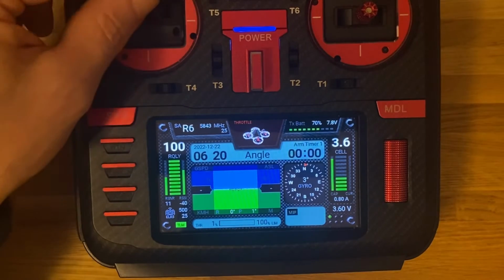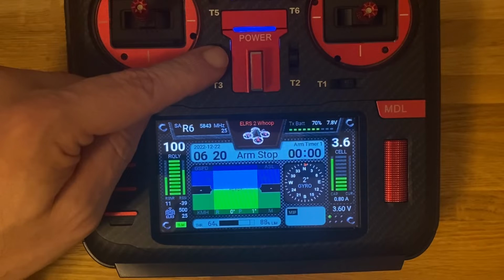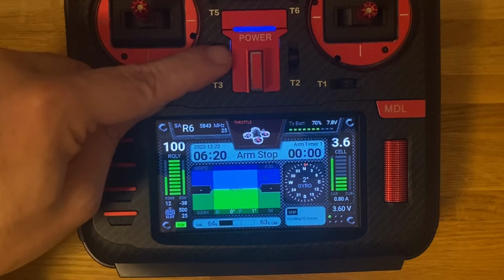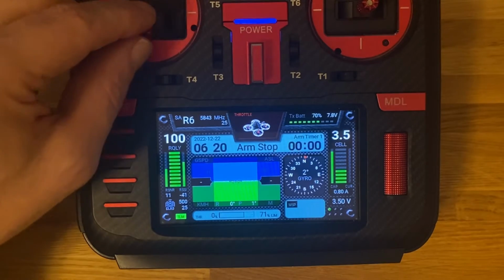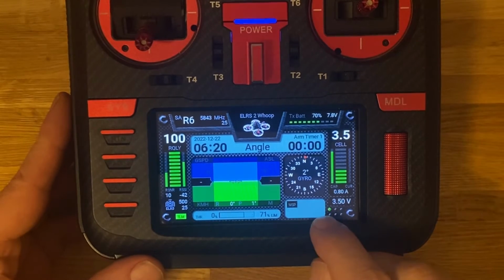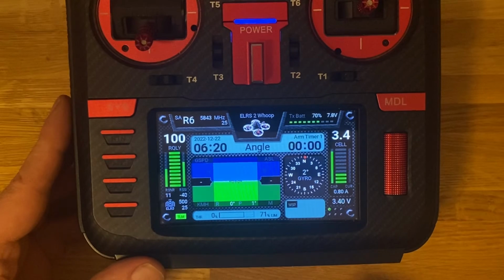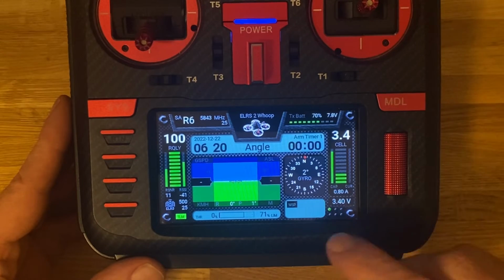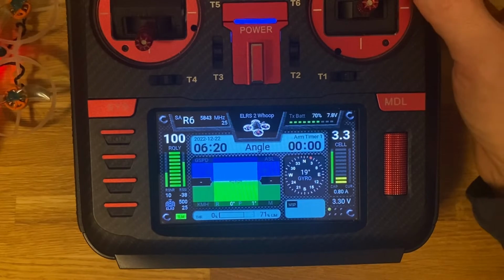Throttle limiter. As you can see, I can see my throttle position, but I have also configured a limiter, so I can limit my throttle input, let's say to 70%, and now I can see all the settings. This is this information, small window. So you can see MSP is still reading the FC to check errors, things like that. Thing is, guys, that it works only if it's not armed, because we cannot mess with something while flying. So if I arm, I think I can.